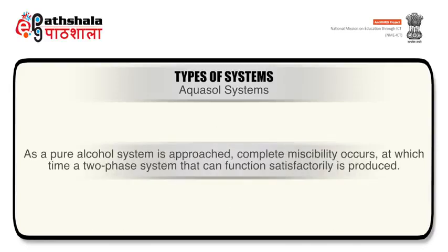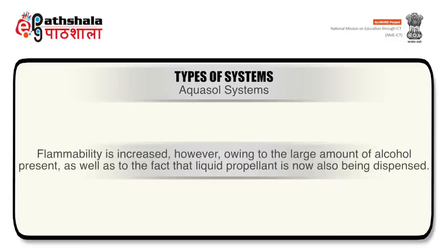As a pure alcohol system is approached, complete miscibility occurs, at which time a two-phase system that can function satisfactorily is produced. Flammability is increased, however, owing to the large amount of alcohol present as well as to the fact that liquid propellant is now also being dispensed.